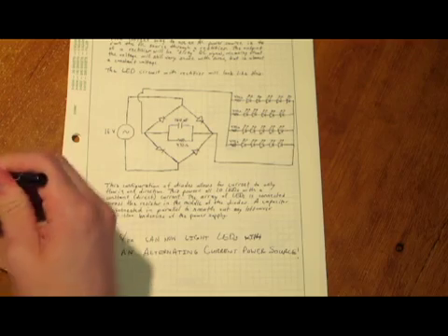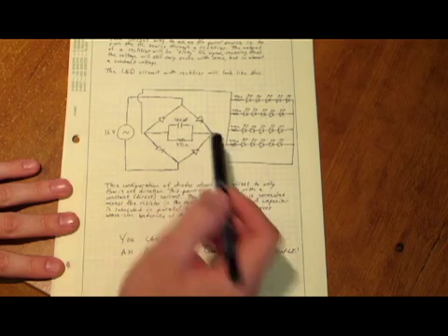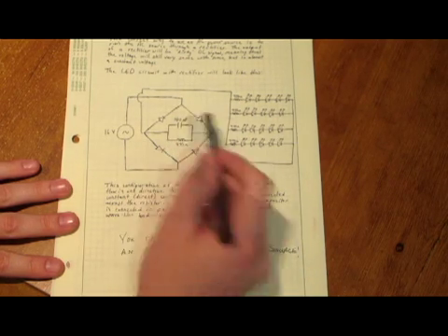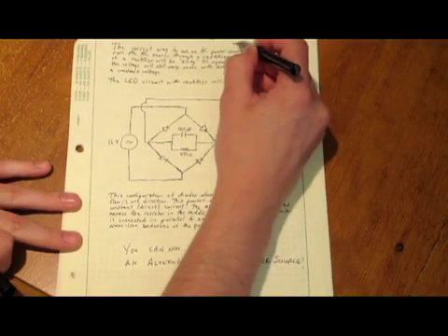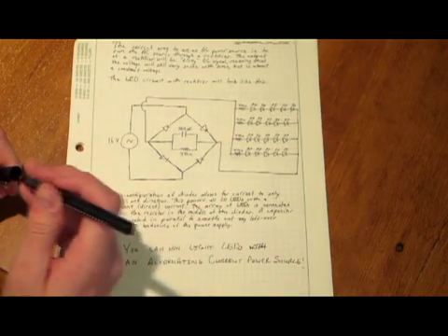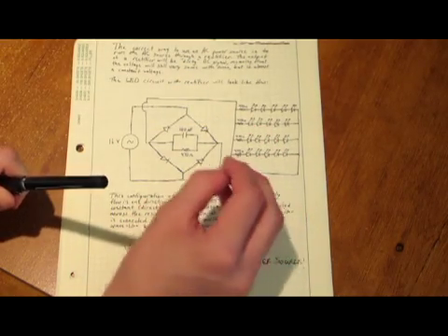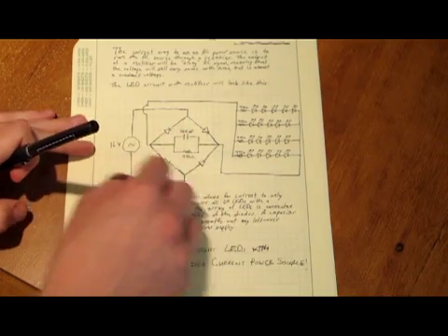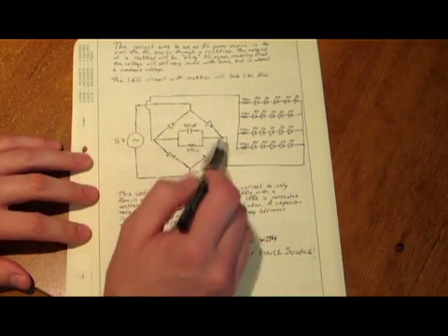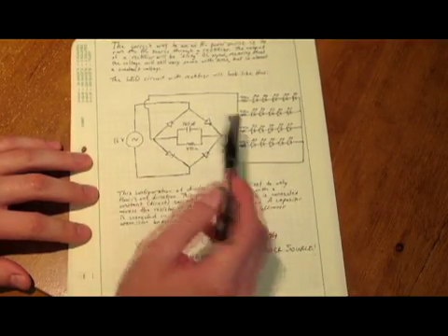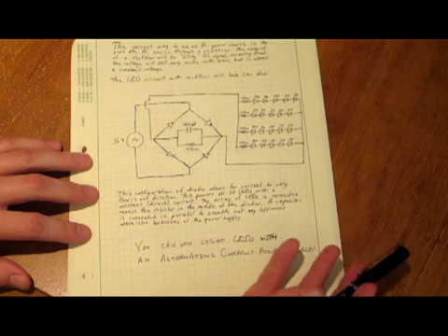Also, this would be your load, and you're powering your load across the resistor in between the diodes, and the capacitor is added just to smooth out any waves, just so you can get even more constant current. And that's because if one side tries to draw too much, it draws it from the capacitor instead of from the opposite side of the power supply, and vice versa. And so with that, this is called a bridge rectifying circuit, and you make it with simple diodes, and that's how you get DC current from an AC current supply.